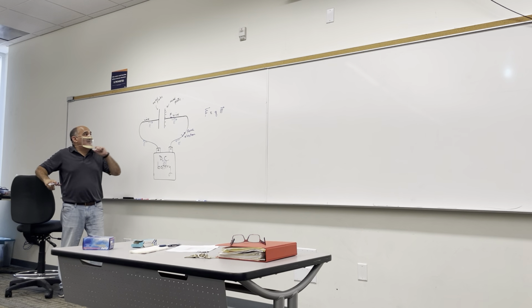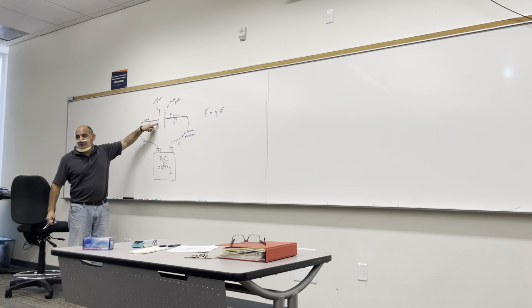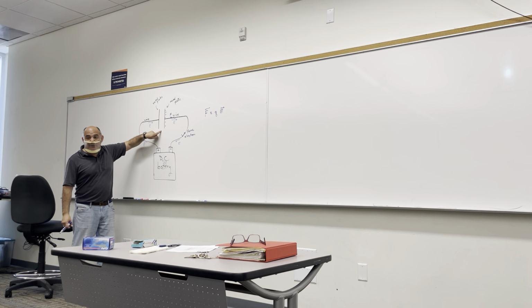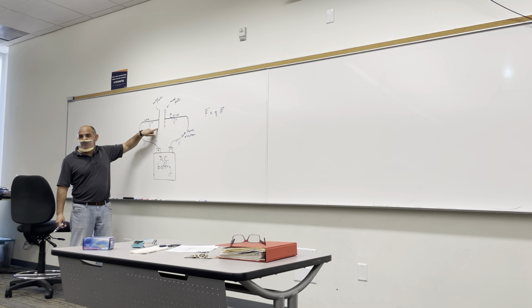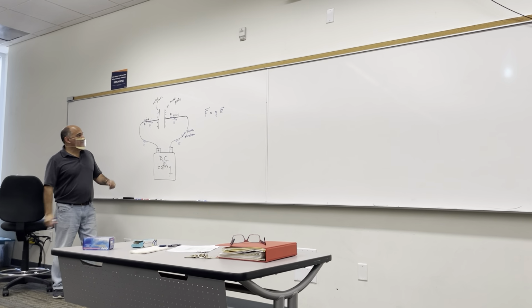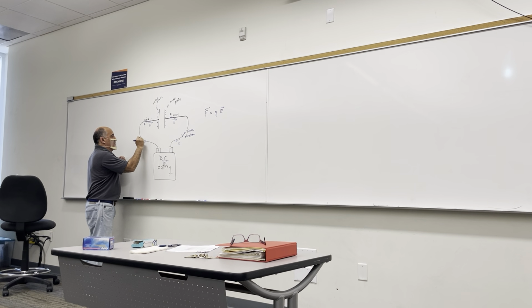And what are those electrons going to do to the conduction free electrons on the other plate that's across it? They cannot go through it because there's no metal connecting this plate to this plate. But it will do what to them? Pull them or push them away? Push them away. So there's another electron here, right? And that's going to be pushed away. And as the electrons are pushed away from this plate, there will be an excess of positive charges left there. And then these electrons will go this way. The force on the electron, right?